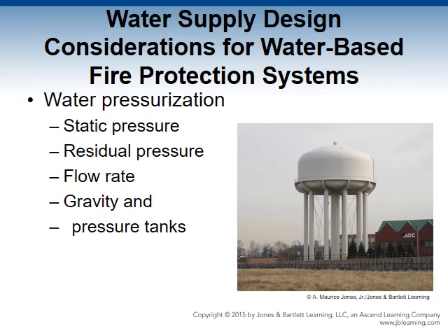They are engineered to withstand constantly changing environmental conditions. Water in public tanks keeps fresh water moving, but water in private tanks will stagnate. In general, tanks are used to supplement the supply of water when the distribution system cannot meet the instantaneous fire flow demands needed to fight fire. They provide an automatic, reliable, and positive pressure water source. As the tank's height above the ground increases, so does its pressure at ground level.